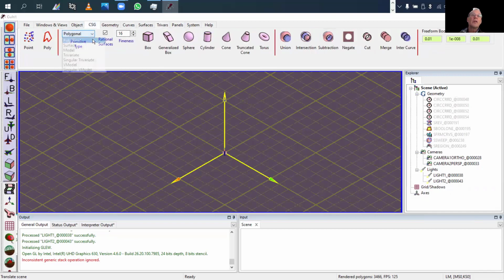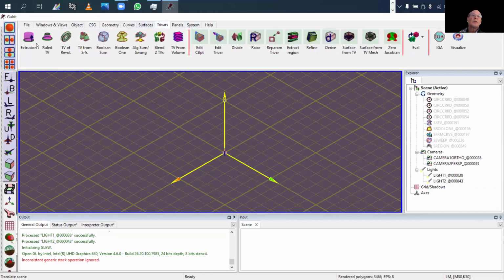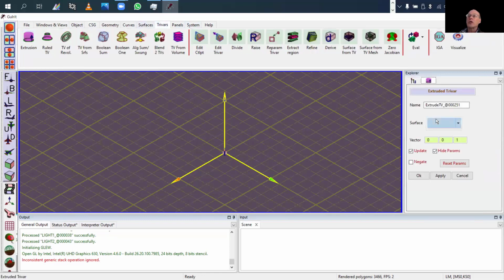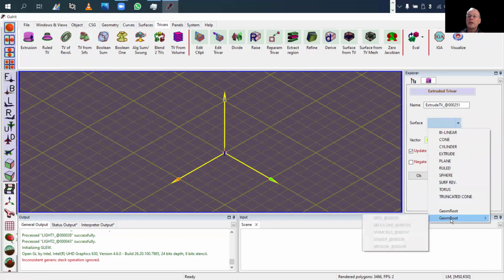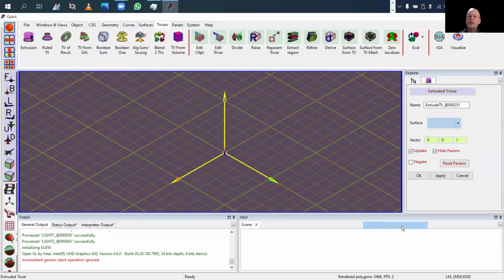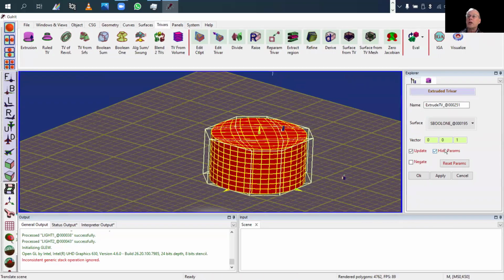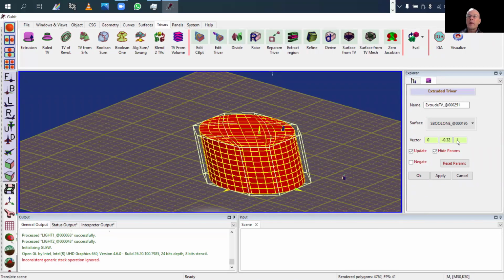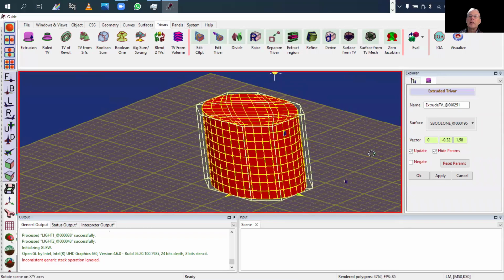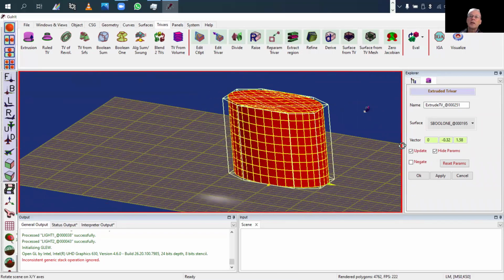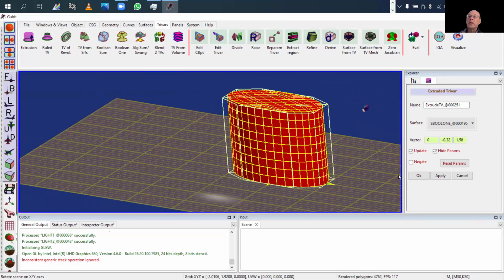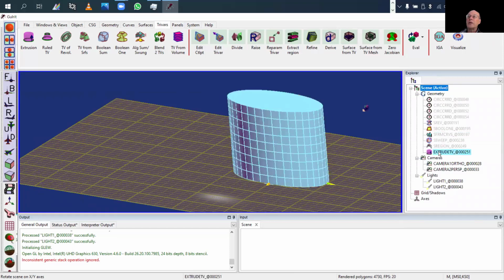We talked about the ability to define trivariates from here too, but you can also use a trivariate constructor like extrusion. For extrusion, I can only select surfaces, and I have the Boolean 1 disk, for example. If I extrude it in the third dimension, I essentially create a skewed cylinder in this case, that is volumetric. It's a trivariate function of three variables.